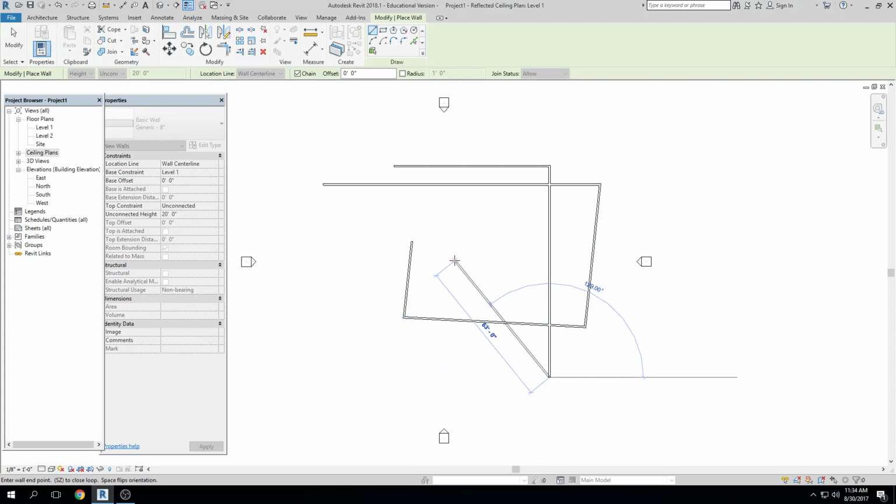No, just kidding. So in AutoCAD, right, when I want to input 6 inches, I just type 6, enter. And it assumes that 6 is inches because that's the default unit in AutoCAD. But in Revit, the foot is the default unit. And so if I type 6, enter, it assumes 6 feet. All right, so you'll get used to doing what I'm going to show you in a second.